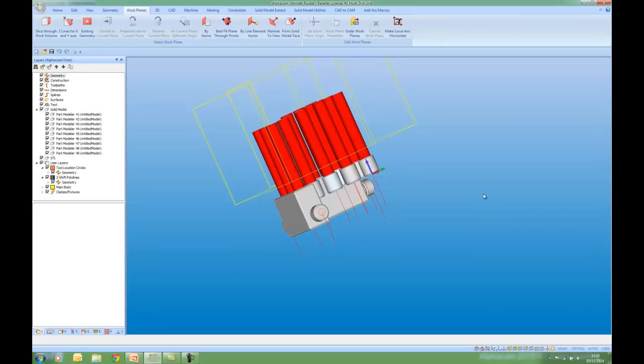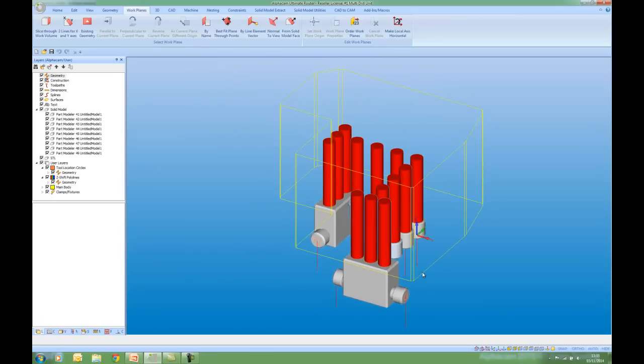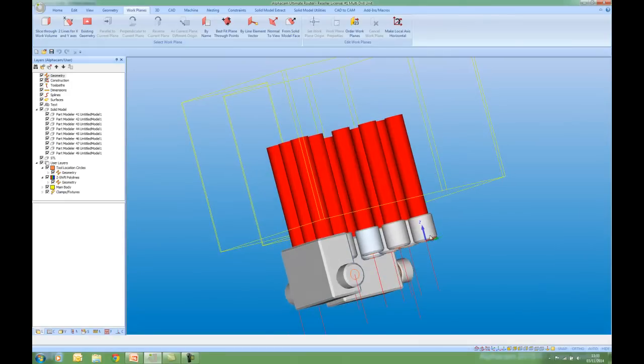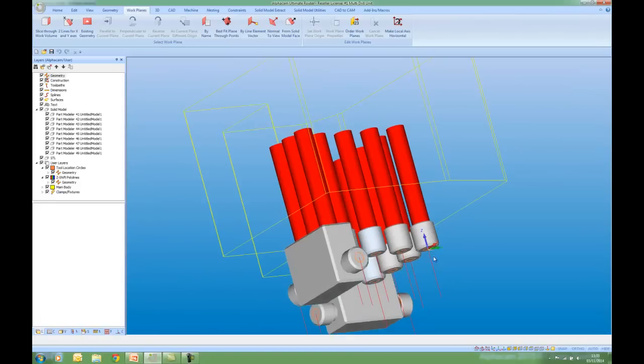So the longer that 3D polyline, the further the unit will come down. What we also have is a 2D geometry here with Z level set that represents the main body of the drill unit, and also I've been careful to put my global X0, Y0, Z0 at my reference point drill position.